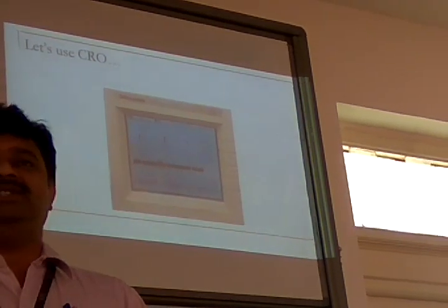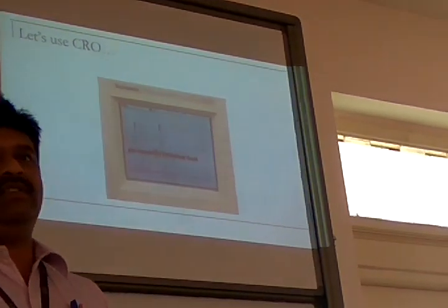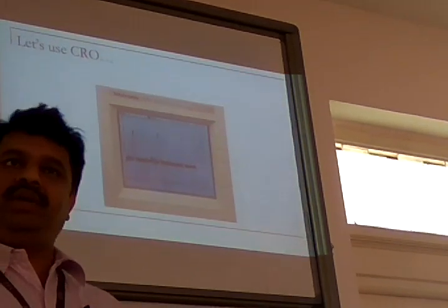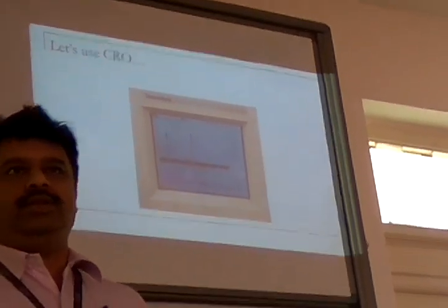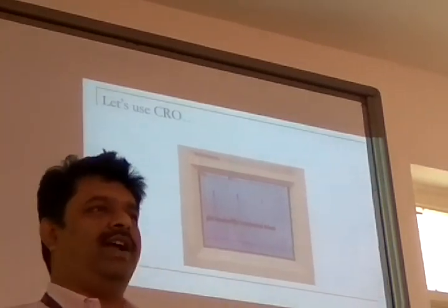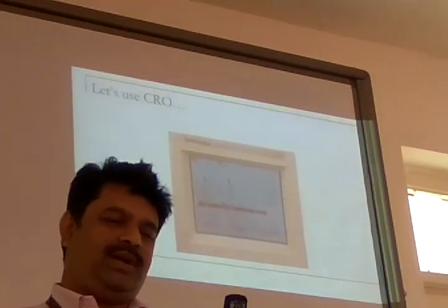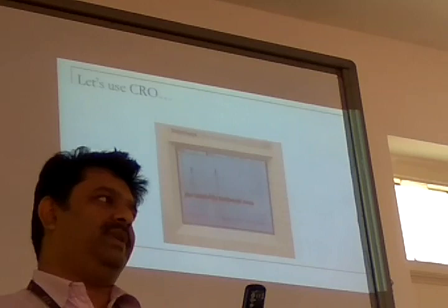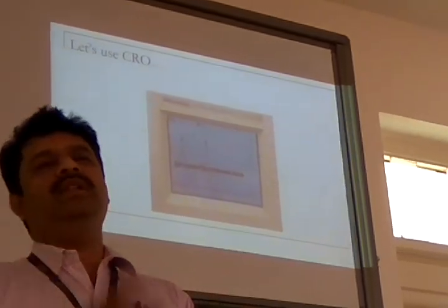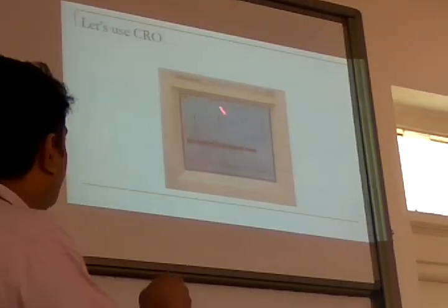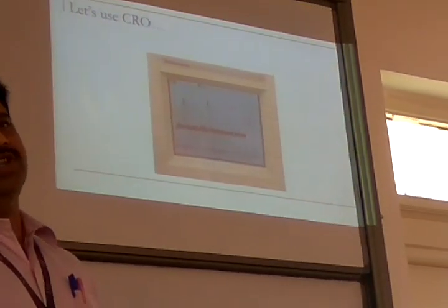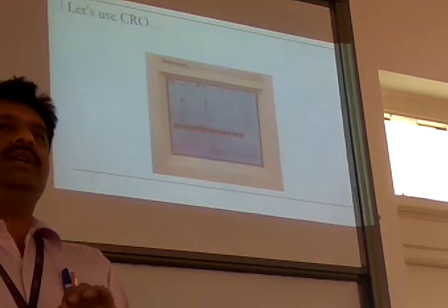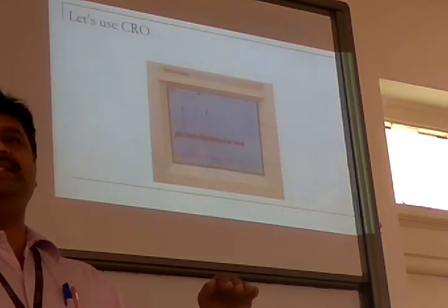But that is not the temperature we want, because the device is already calibrated for a pure DC signal. Now if AC noise is coming, you will get a wrong reading than what you expect. You expect some reading, but it will show some other reading. You will not know whether it is a wrong reading or right reading when you have only one thermometer and you are simply measuring a component's temperature. It will show some temperature. That result will be misleading. So we would like to have a filter to remove all these kinds of noise so that my signal is purely a DC signal in this case.